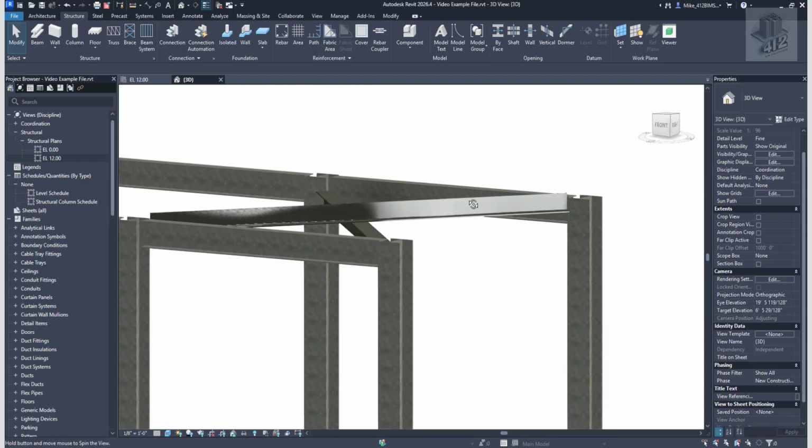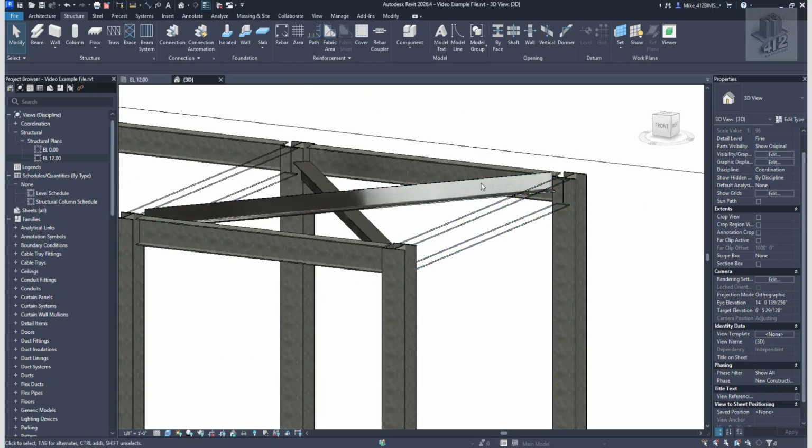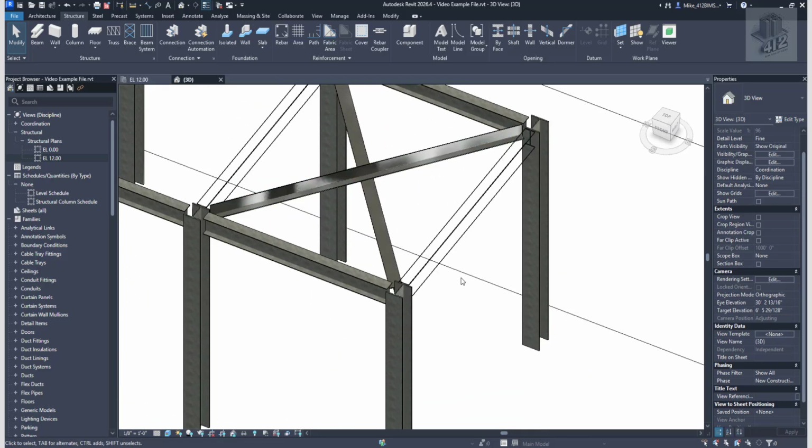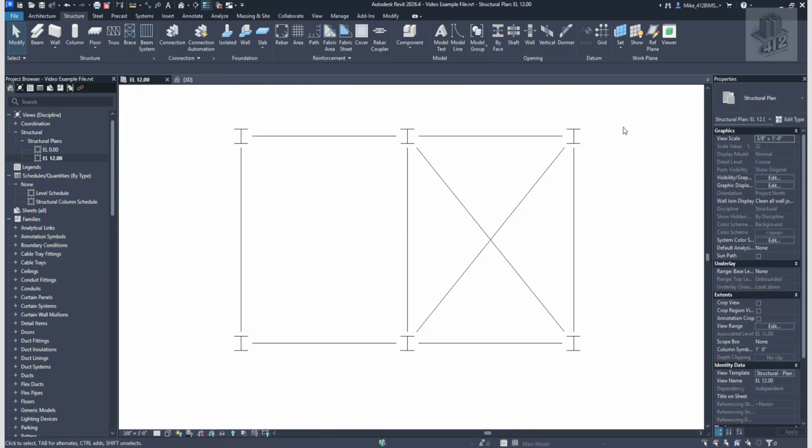And now you have cross bracing here. Again, oversized, I know. I'm just trying to go through how these work. So now in the left bay, I'm going to start adding some channels in here. And that's where you've got to watch with the justifications and the location line settings.